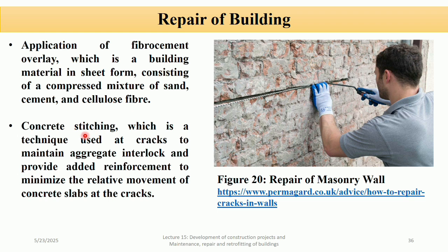In this, it is a technique used to connect both sides of a crack using metal rods or stitching bars inserted across the cracks, embedded in epoxy or grout. So it maintains aggregate interlock, prevents further widening of cracks, and provides structural reinforcement.